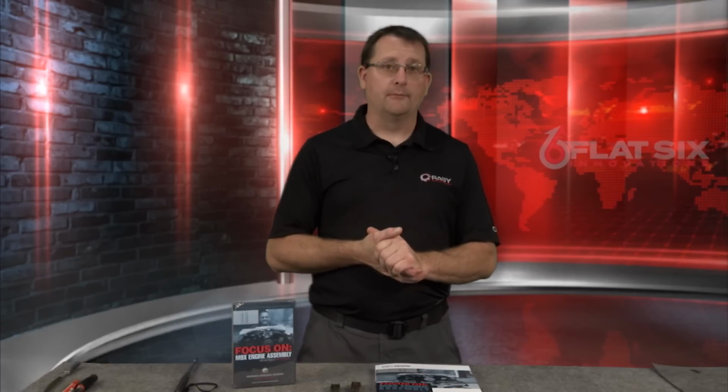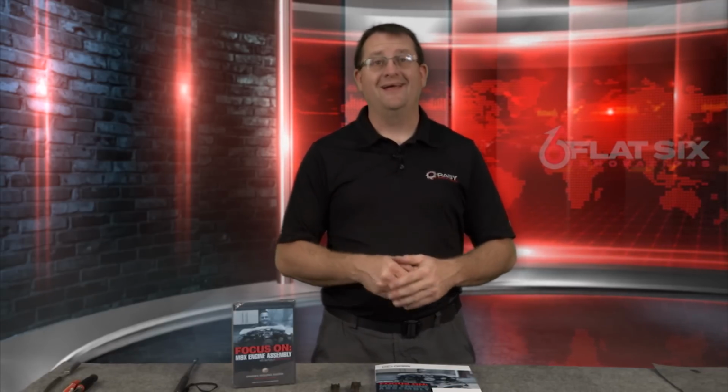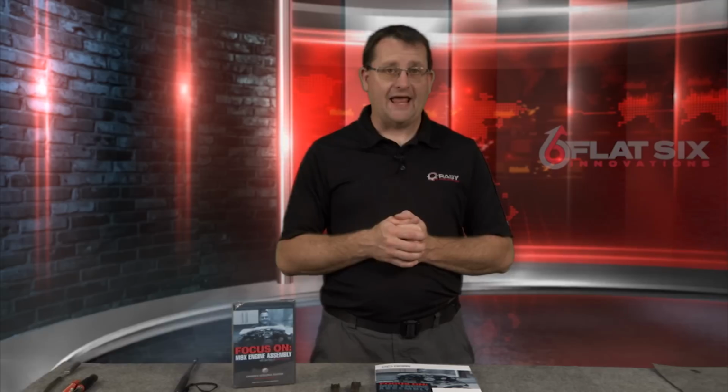Camshaft deviation problems are not an absolute downer to the engine from a global perspective. You're not going to have to perform a rebuild because of this problem unless you drive the car to death, meaning you keep on having camshaft deviation symptoms, you know you have a problem, you've got constant check engine lights, whatever the case may be, you avoid taking action when you found things in the oil, and you wear these chain guides to the point where they snap, or they wear completely through and into the chain adjuster. When that happens, it creates a lot of ferromagnetic wear debris. That wear debris takes out the rest of the internals of the engine as a global instance, okay?